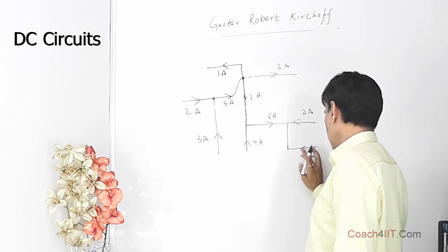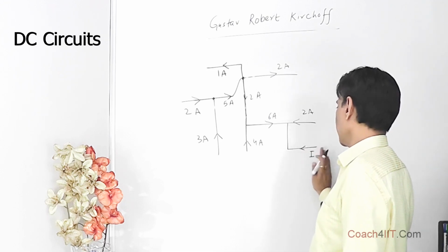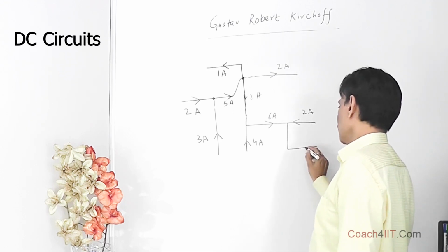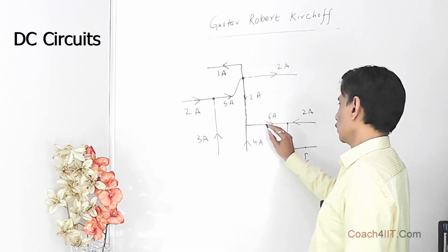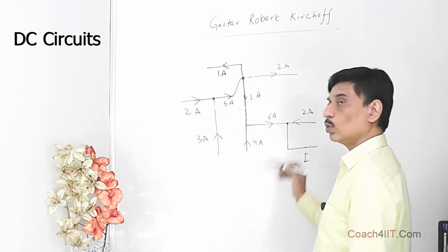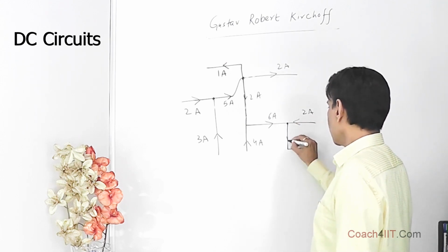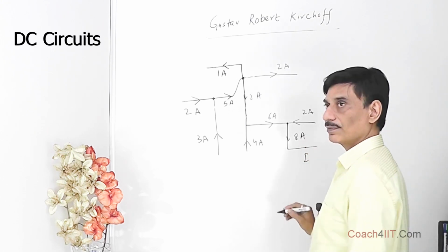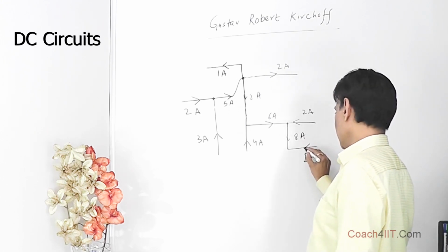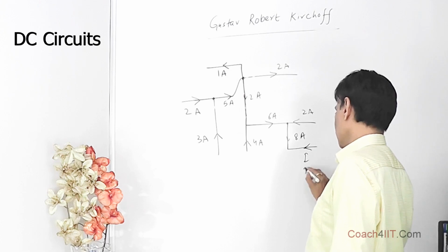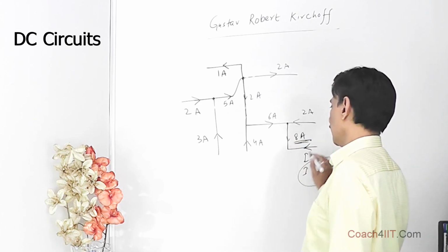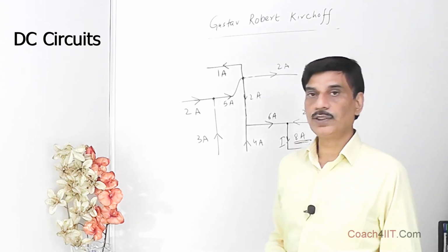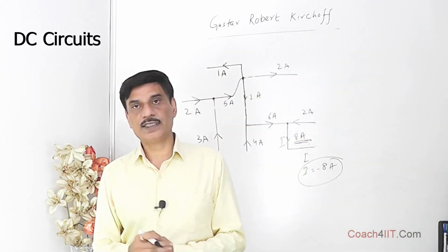If we talk about the direction of current, it will come out to be negative, or if you simply have to find the direction of current in this wire: 6 ampere is coming from here, 2 ampere is coming over here. The total current approaching the junction is 6 plus 2, 8 ampere. So the current should be 8 ampere over here. If the direction is given as shown and someone asks what the current is, we'll say I is equal to minus 8 ampere. Or if we say the current is in this direction, we simply say that the current is 8 ampere in this direction. So this is how we can use the junction rule to find the current in the various arms of a bigger network.